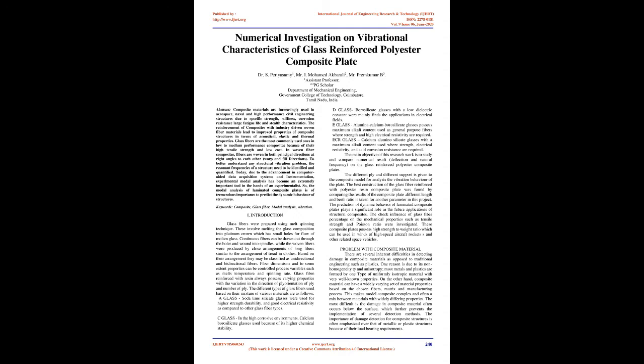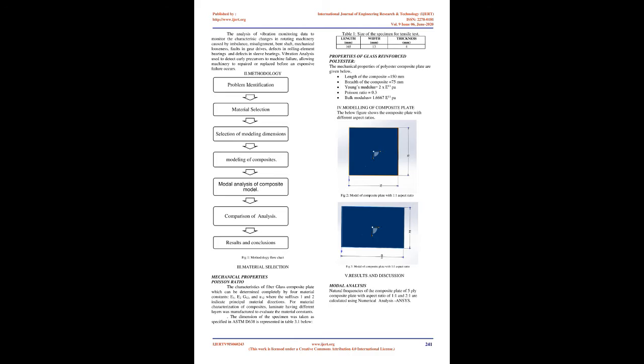In woven fiber composites, fibers are woven in both principal directions at right angles to each other, warp and fill directions. To better understand any structural vibration problem, the resonant frequencies of a structure need to be identified and quantified. Today, due to the advancement in computer-aided data acquisition systems and instrumentation, experimental modal analysis has become an extremely important tool in the hands of an experimentalist. So, the modal analysis of laminated composite plates is of tremendous importance to predict the dynamic behavior of structures. Keywords: composite, glass fiber, modal analysis, vibration.